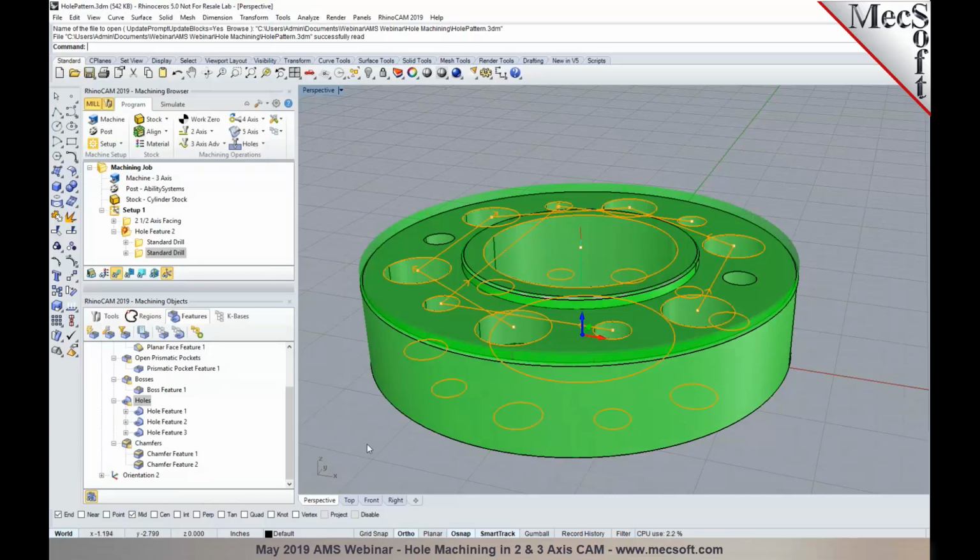Just to summarize what we covered so far: the different selection techniques using points, arcs, circles, using face edges, flat areas from solid surface mesh geometries, and predefined regions from solid surface mesh geometries. Predefined regions can be created using curves, face edges, as well as flat areas.